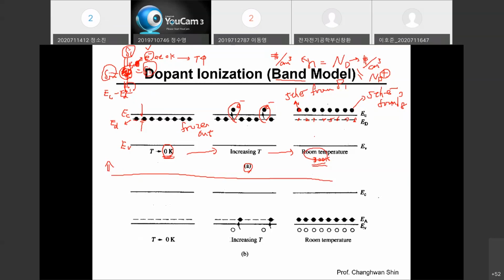So why is doping very significant in silicon devices? Suppose that you're a device engineer or process engineer fabricating a 1Z third generation DRAM product, and your boss has asked you to implement 10 to the 15 free electrons per unit volume. What is your engineering solution? Well, if you'd like to control and modify the total number of free electrons within a silicon crystalline material, always think of the doping technique. Doping is very powerful in terms of modification and controllability of the total number of free electrons. The total number of dopant atoms is always equal to the total number of free electrons that you can handle.